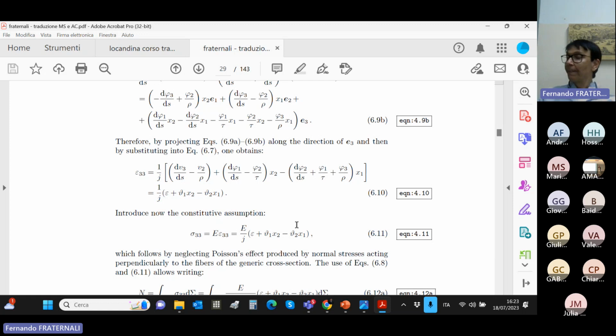Another way of justifying this assumption is that the material of the beam is not isotropic, but transversally isotropic, and has infinite elastic moduli in the transverse directions. We could always do this to account for our assumption of the rigidity of the cross section.